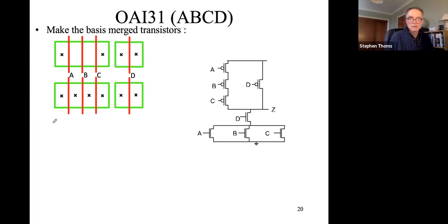And then we need to do the same for the NMOS. Now, on the NMOS side, we've got A, B, and C. And again, A, B, C for the gates. And remember that in parallel, we needed to have a contact in between, because what we're now going to end up doing is this one here will actually be connected to this, and this will be connected to this. So you can see that here, this is your ground, VSS. These are all connected to each other.